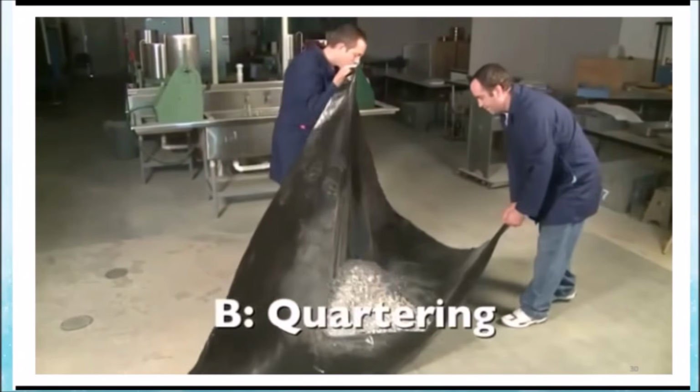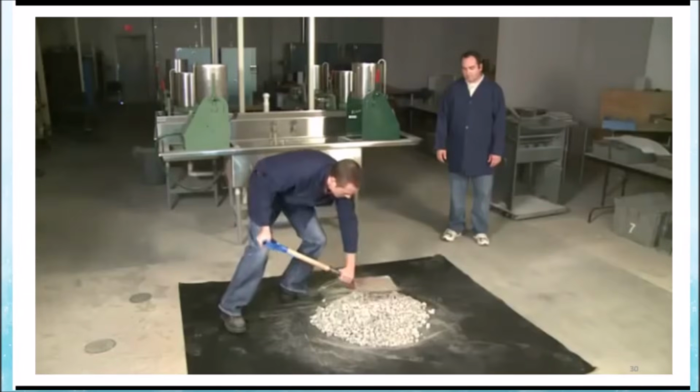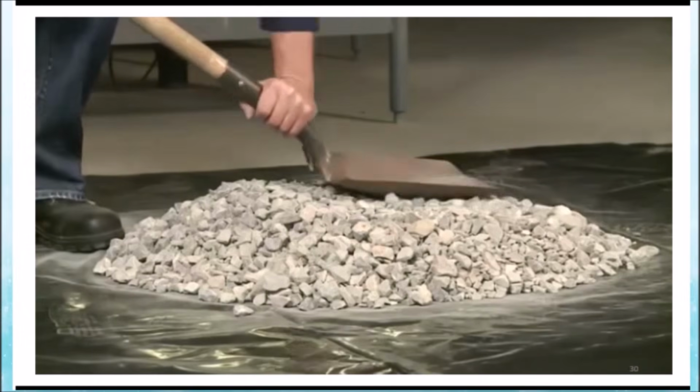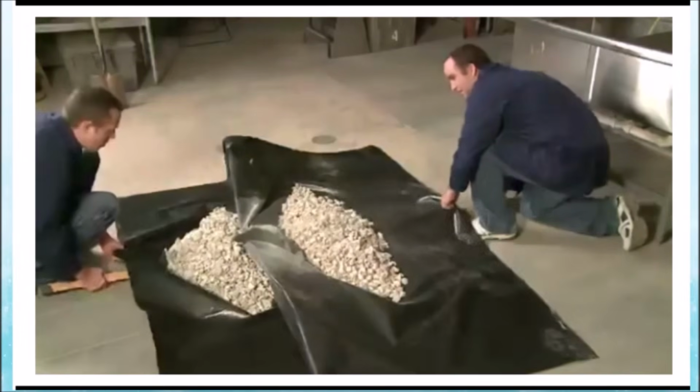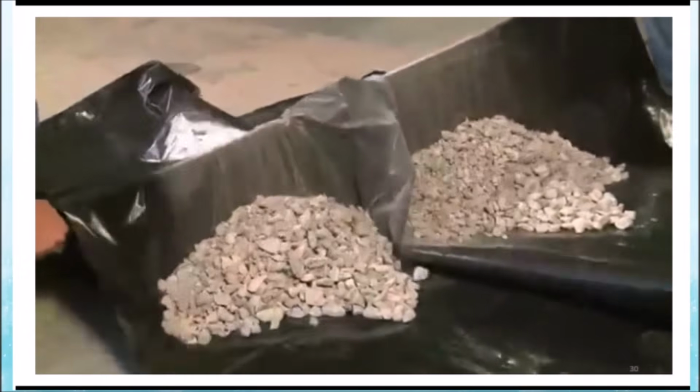When using Method B, the procedure is the same for either coarse or fine aggregate. It will be more difficult to flatten a conical pile of aggregate containing coarse particles. Extra care must be taken to maintain the material composition of each quarter as much as possible.